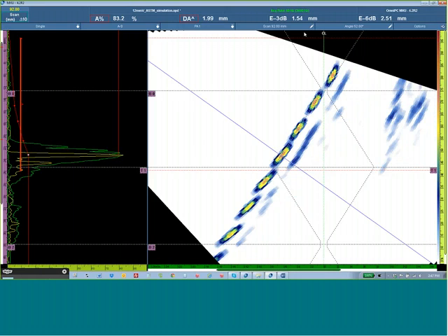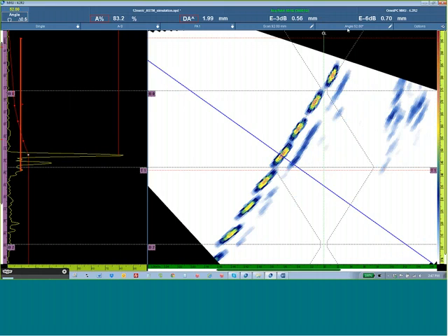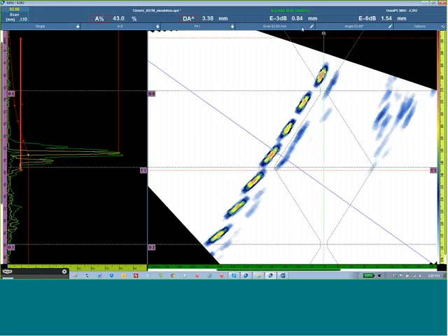The A-scan envelope readings for the -3 and 6 dB drop show me the vertical height sizing window, or also called the echo dynamic, that affects sizing on the weld bevel or at any position inside the weld. The decision to use a 1 degree or half a degree or 0.2 degree inspection is directly related to this.